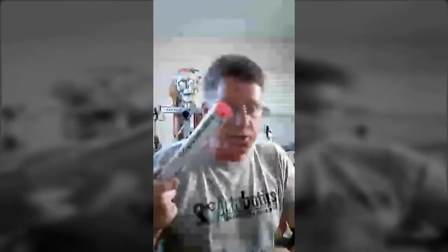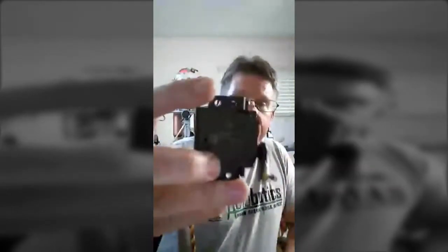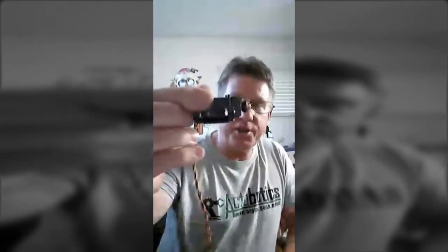And this stuff is magical. I use it all the time for making platforms and extensions and filling things when I'm building a lot of these props. Once it sets up, and it sets up pretty quick, 15 minutes or so, it's sandable, it's fileable, it's drillable, it's tappable. So if you still want some more rigidity and aren't comfortable just with having this thing glued down into that epoxy, you can drill a couple of holes in these side holes here and tap and drill so that you can attach a couple of screws there.